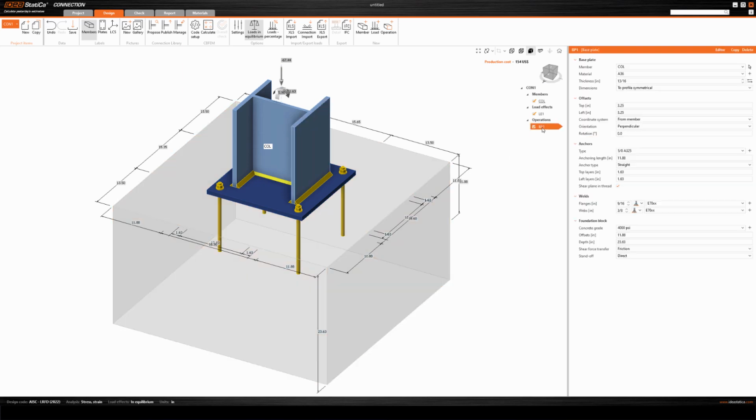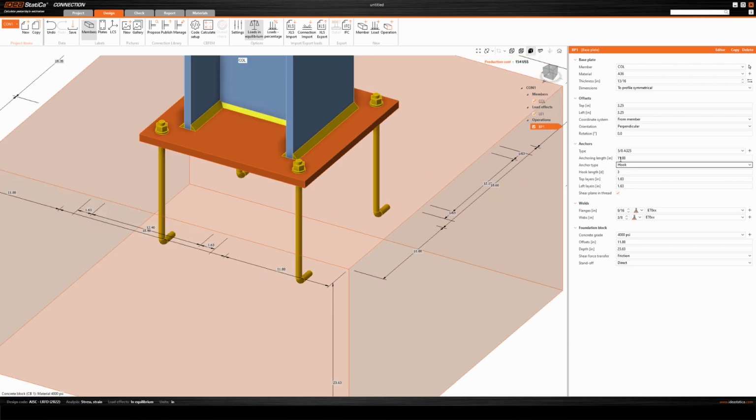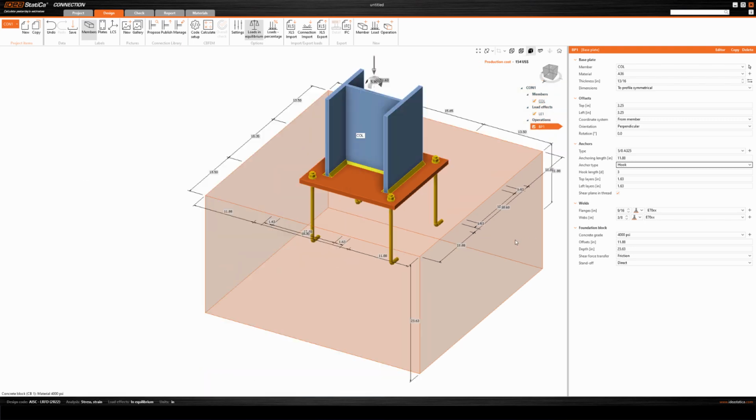And when you are defining base plate, if you remember here, I can select my type of anchors. Okay, so here in this option we have anchor type. By default it's straight, and now as you see we also have added the hooks. You can just click there, and you have full control here for the dimensioning of those hooks or L shapes.